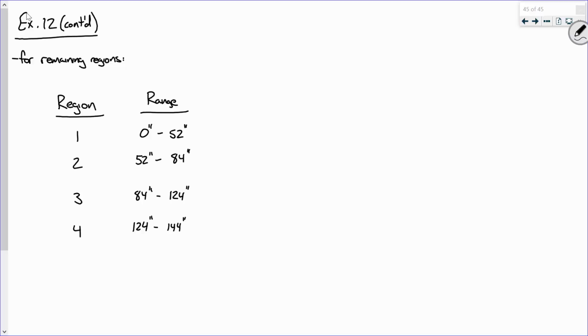So S. We have what, 4-inch spacing? We have what, 8-inch spacing? We have 10-inch spacing, and then what's the spacing out in that center region? There are none. There's nothing there. So we need VS. Now, we did this for the 4-inch spacing, and we got what, 79.2?